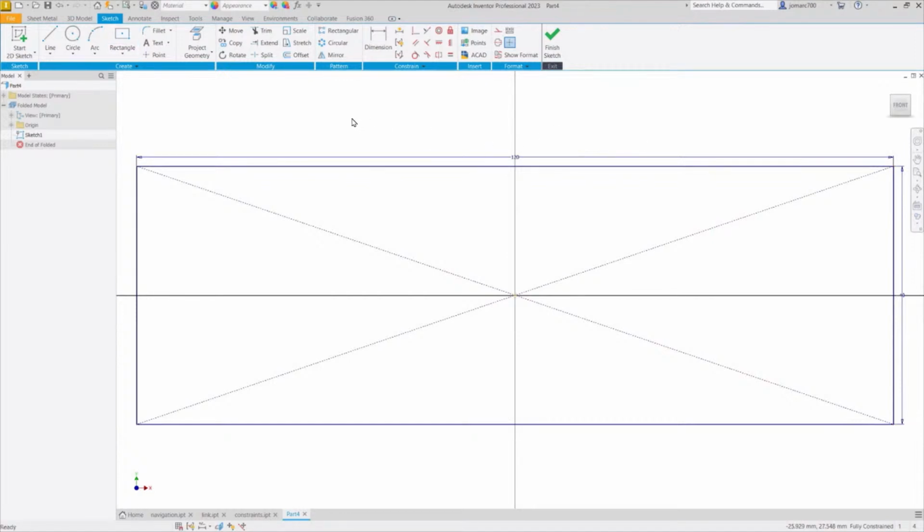Next, let's create 2 circles. Shortcut key for that is Control Shift and C. Let me create this first circle over here, next one over here. But this time, notice once more that dimension which is currently highlighted. I'm going to key in 10, hit enter. Next, this circle and this circle should have an equal value. Heading up to constraint, selecting equal, selecting this circle and this circle.